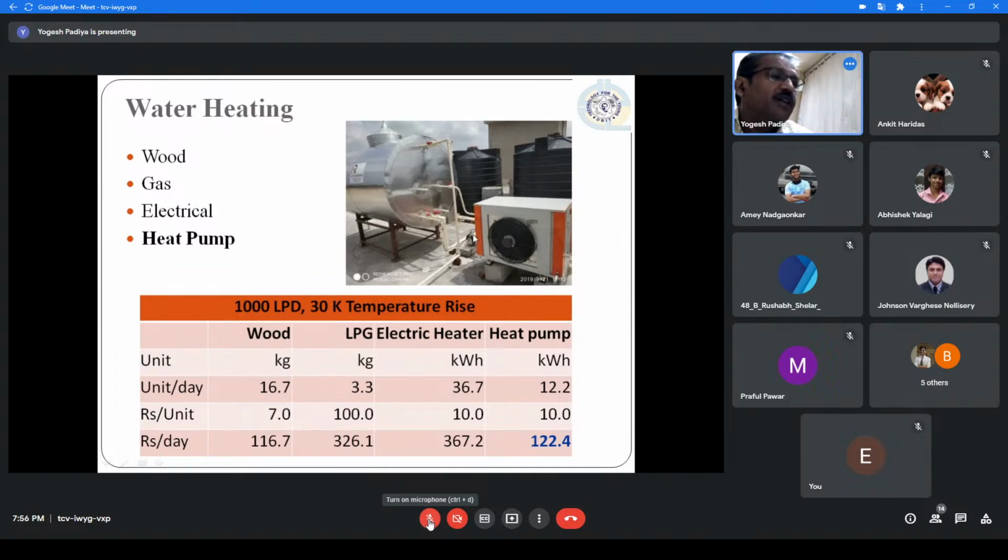If you put 2 kilowatt, then you are getting 5 kilowatt of heat. In the case of an electric geyser, you are paying for 5 kilowatt, but in the case of a heat pump, you are getting 5 kilowatt while consuming hardly 2 kilowatt. It means your light bill will drop from 36 to 12 kilowatt. It means your light bill will drop from 360 to 120.